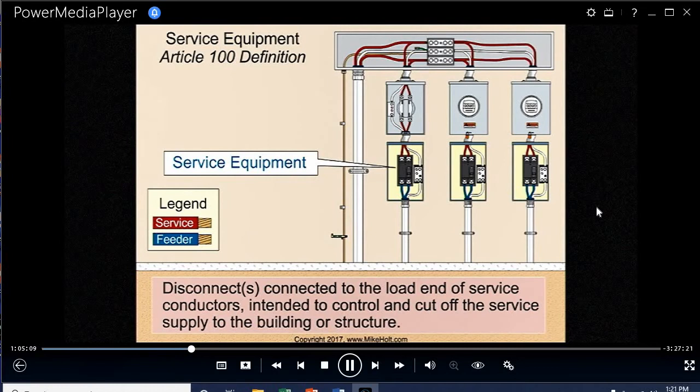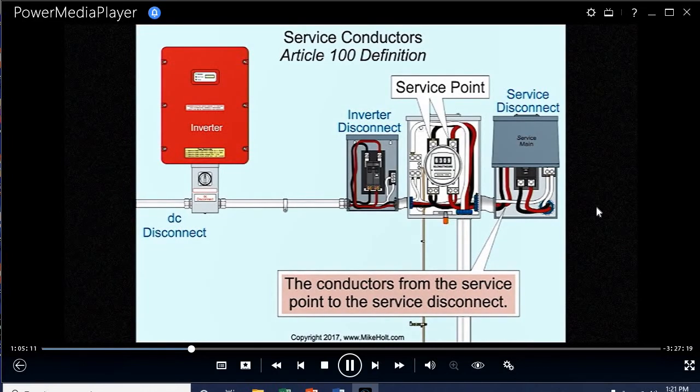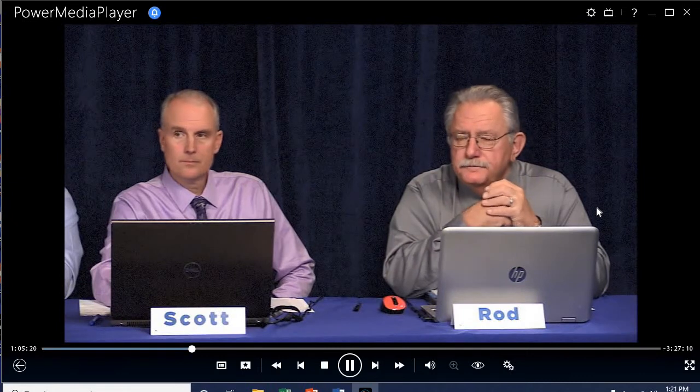So we'll talk more about this as we get along, but you can see how subtle points are a big deal. So for 2020, Brian, let's make a note to maybe make something that it can terminate to service equipment. Is that strong language where it says you can't do it, or is it just not there? We're going to see. The answer is no, you cannot do it. But then we need to talk about where it says you cannot do it. And really what it is, 250.142, because you can only do it at service equipment. Well, that's not service equipment.